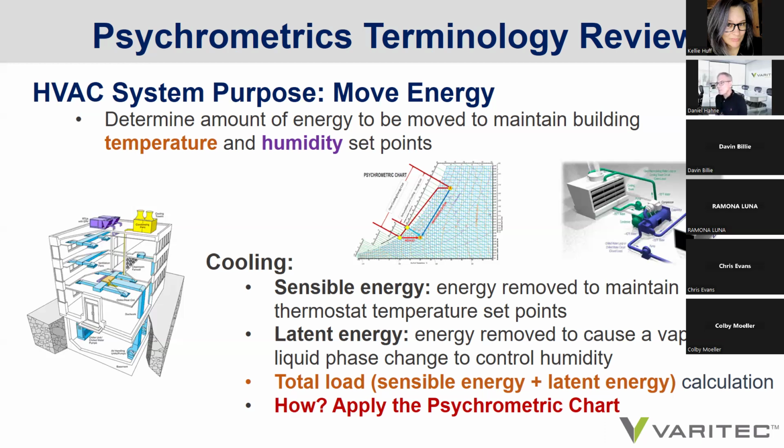from the building as possible as the building gains throughout the day and deposit that energy outdoors, as well as any humidity buildup during the day that needs to be deposited out of the building in order to maintain relative humidity conditions during our wet times of the year. So in order to do that, we need to calculate the amount of total load, which is defined as the sensible energy plus the latent energy in the building.